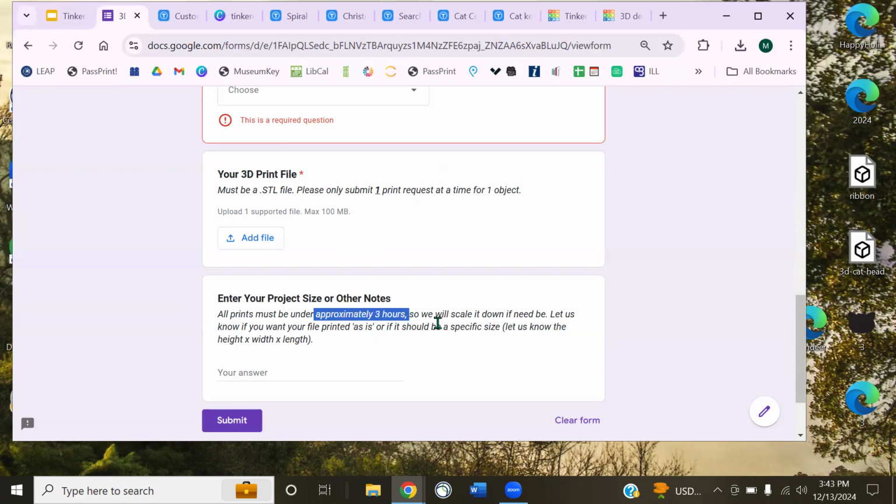This is one of the limitations that we have. We have a print time limit. So it's a 3-hour block that you can use in a given object request. If the object that you have isn't scale sensitive, we'll just automatically scale it down if it comes to us and it exceeds this time limit. So we can do that. And that's also why I mentioned the column scaffolding that's printed beneath something that's floating. Because even if you have a quote unquote small object, if it's printed floating up and all the scaffolding takes up a lot of time, then we'll have to scale the whole thing down.